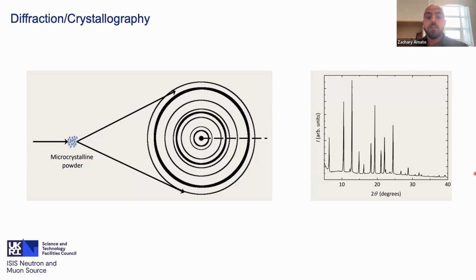And these peaks that you see, that's where you get your information of your crystal structure and also what's in your sample. So the peak position, where they are, will have to do with your crystal structure, the phase of your material, what's in the material, because things will have a specific fingerprint in a sense. The intensity will give you some information on atomic parameters, if there's any preferred orientation, and the shape of them will tell you how crystalline your material is, if there's any disorder.